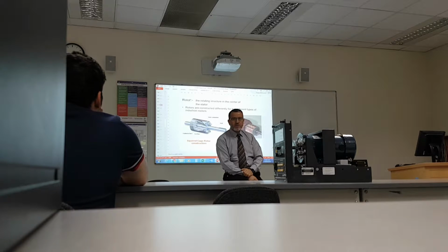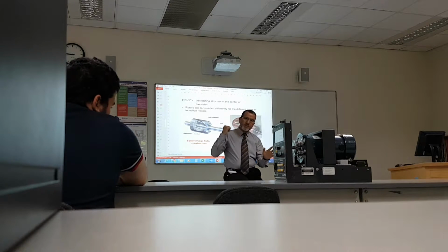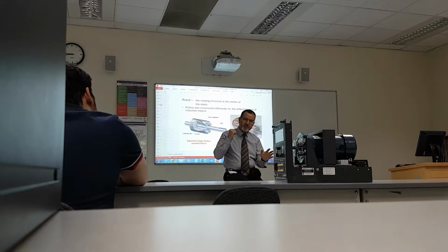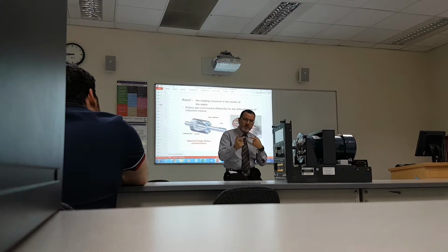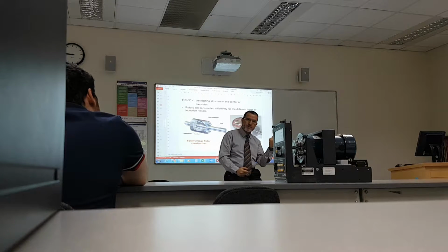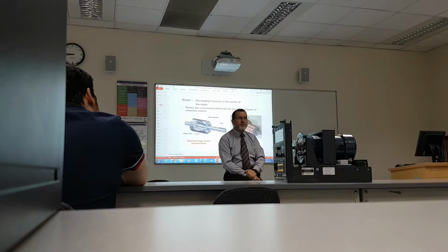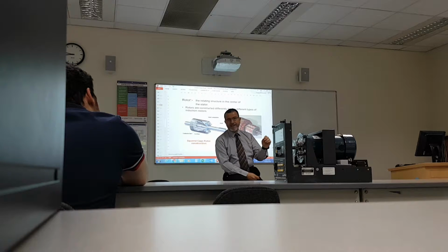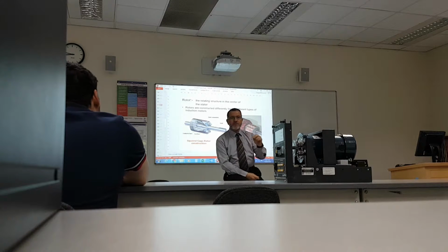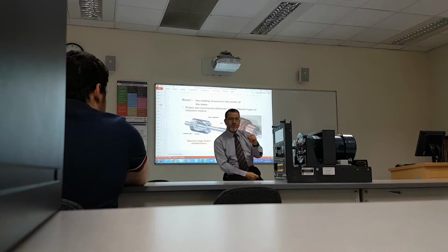I think what he's talking about was synchronous. Synchronous, if you have too much load, then it slips. Well, yes. But in our discussion, we're talking about induction. Right? But with synchronous, there's pull-in and there's pull-out torque. Pull-in torque is what? Always think about it as pull into synchronism and pull out of synchronism. That's why it's called pull-in and pull-out.